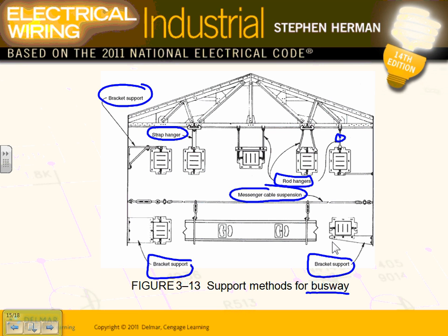These are not 15 amp plug-in busways that you can install. These are major equipment, guys. So you start with 225 amp, then 400, 600, 800, 1000, 1200, 1350, 1600, 2000, 2500, 3000, 4000, and 5000. Everybody can see the standard sizes for the most part. These will be the ones that we're going to be using when I do calculations about busways. When you size a busway, you're going to go to this sheet.